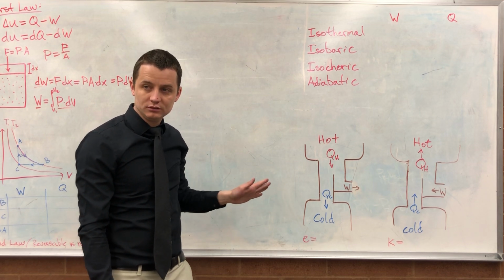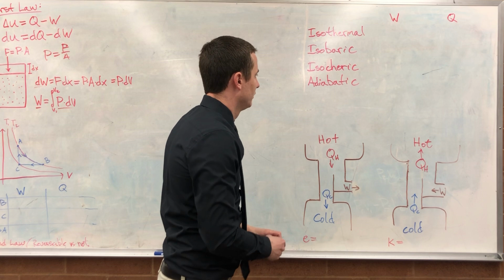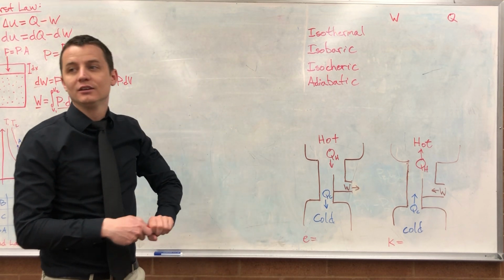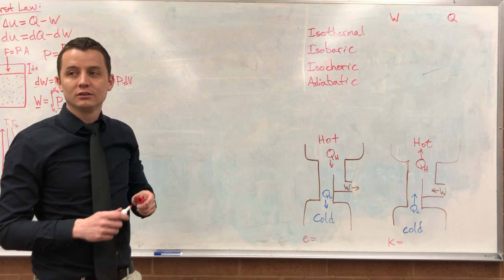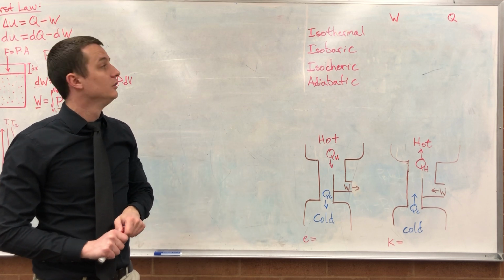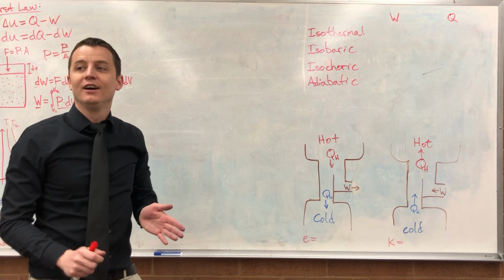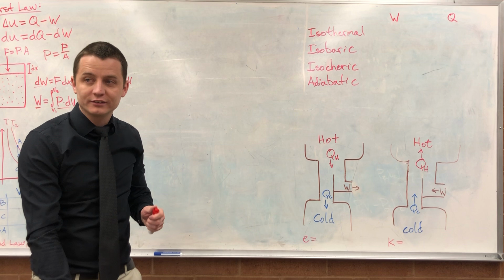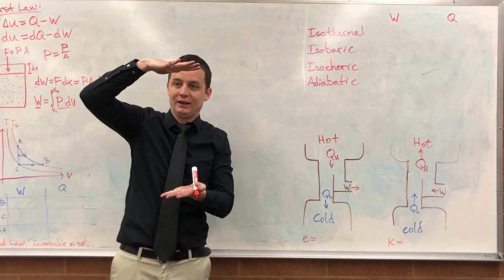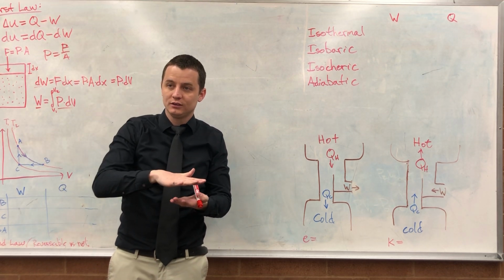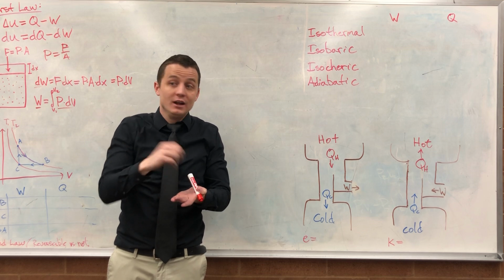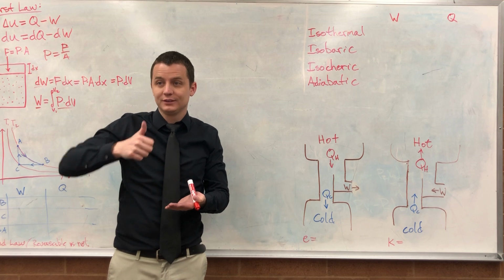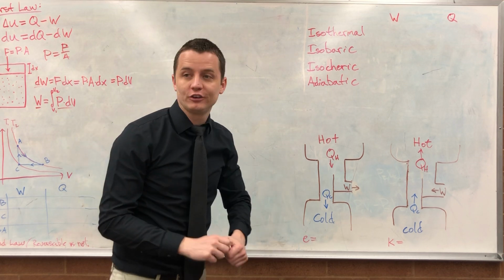Oh, so W is 0. No heat is added, Q is 0. Well, if work is added, then that's adding heat. Not necessarily. I can do work on a system without adding heat. If I have a piston and I suddenly compress it, I did work on it. There was no heat added to the system. The temperature of the system goes up, so the internal energy goes up. Don't get confused between heat and internal energy.